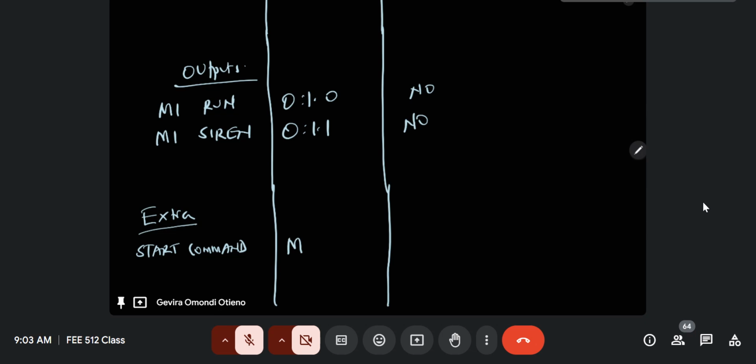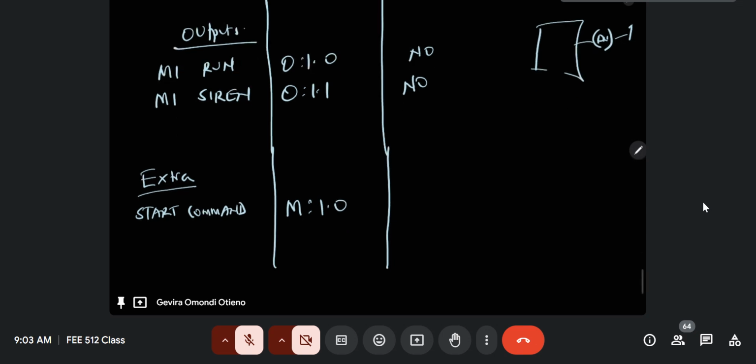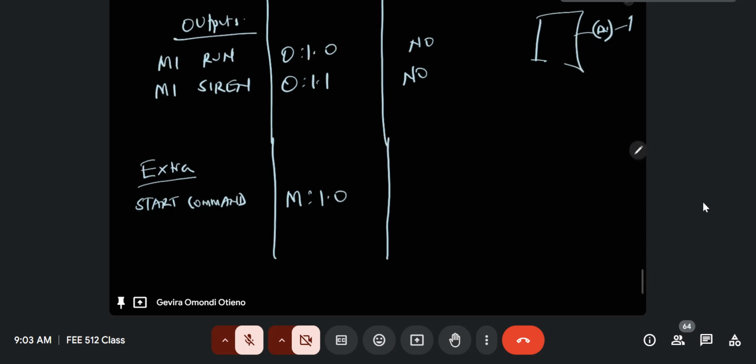So it's not an output, it's not an input. It's just memory, so that we just know that whenever we have achieved the timer, so when the timer done bit goes to 1, meaning the output of the timer, remember the done bit, we are done counting. When that done bit goes to 1, then the start command is given that logic 1. And then, of course, the motor picks up from there, and then the motor starts. So that's why we are committing this to memory. It's a command. It's not a button. We commit it to the memory of the PLC.